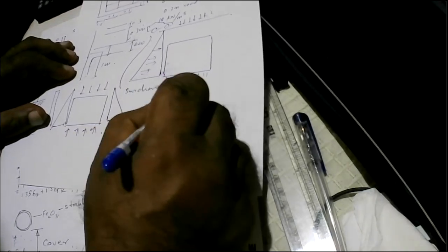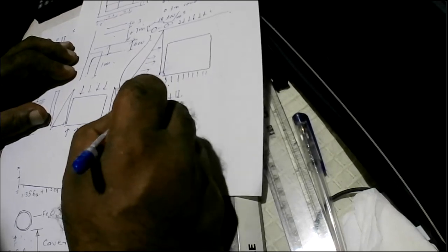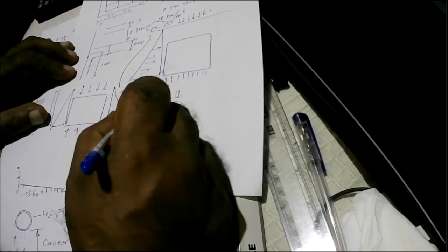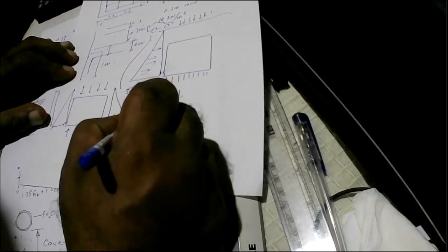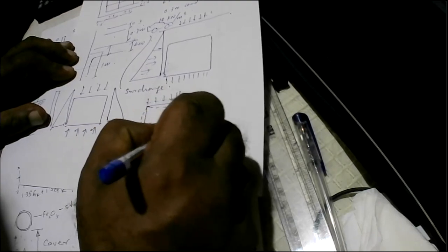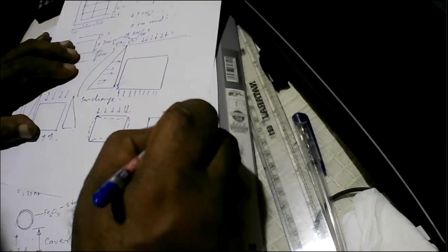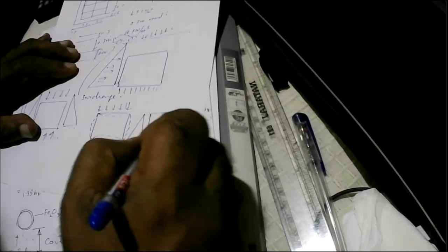One possibility is that the box culvert is loaded fully here, and this soil pressure is something that we assume might not act with the same intensity. In such a situation, the box culvert will behave like this, and then it will go on like that. On the other hand, there's a possibility that the maximum soil pressure is acting, but we don't have any live load here.